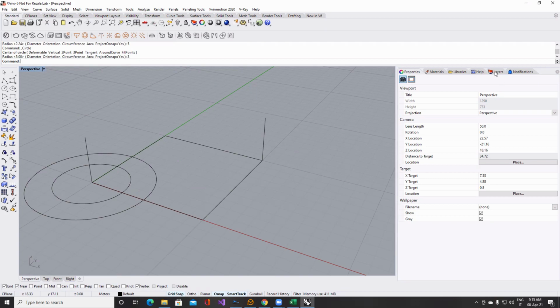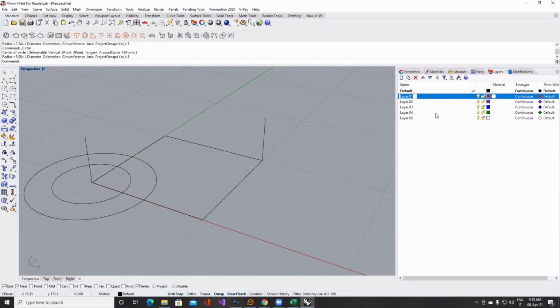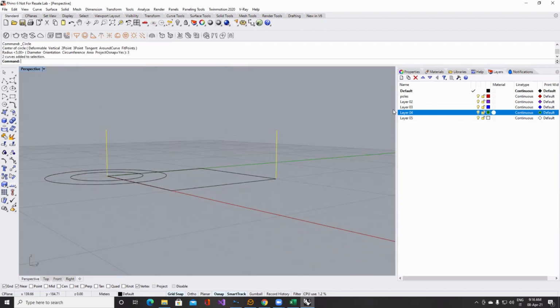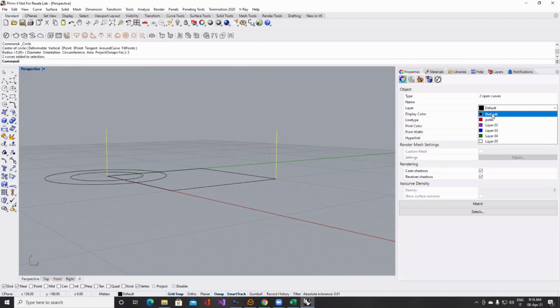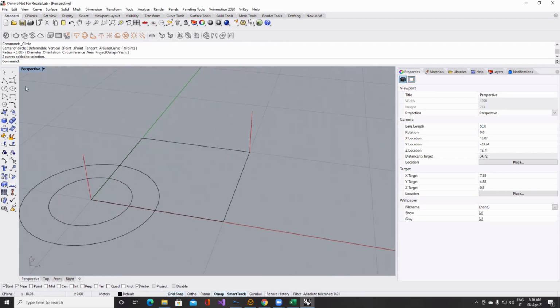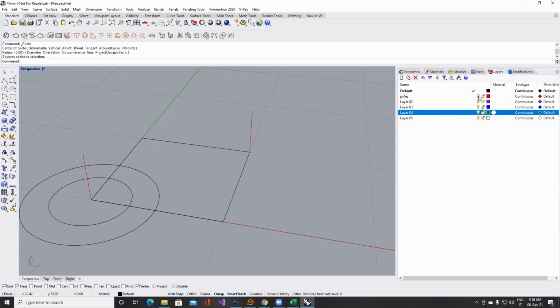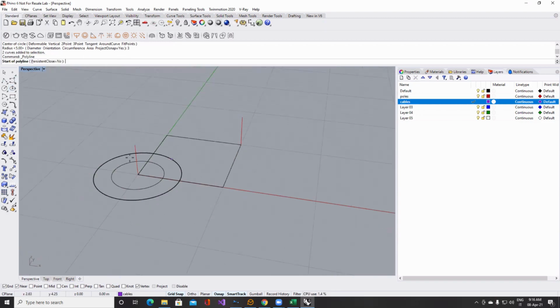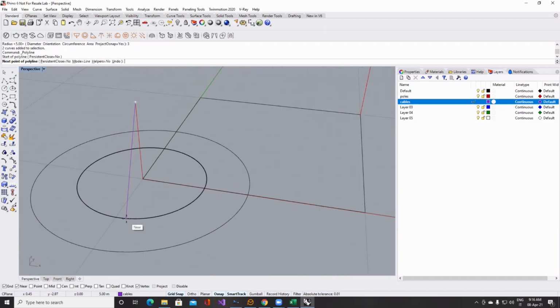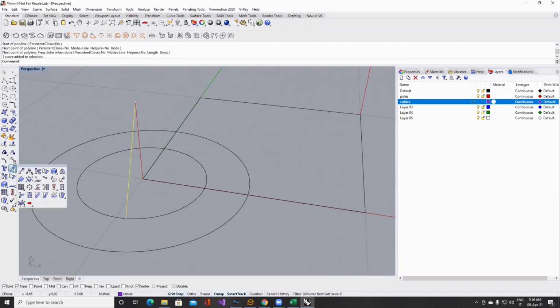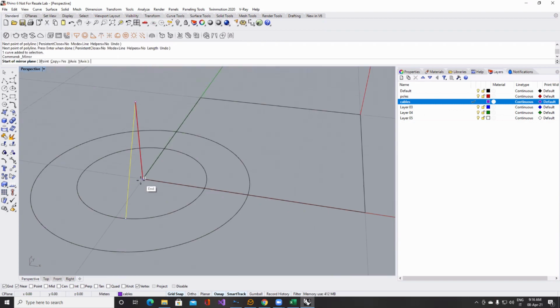And let's go to the layers and poles. These 2 elements go into the poles. Then let's make into the layers, I will make cables. Activate the cables and draw 2 stay cables here. I will make a mirror, so we have a symmetric model this time.